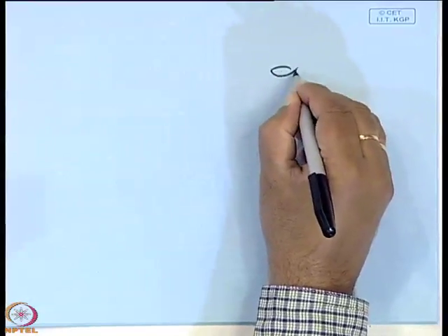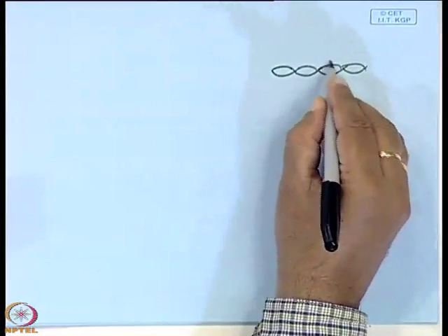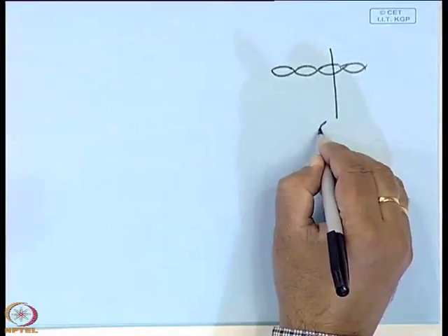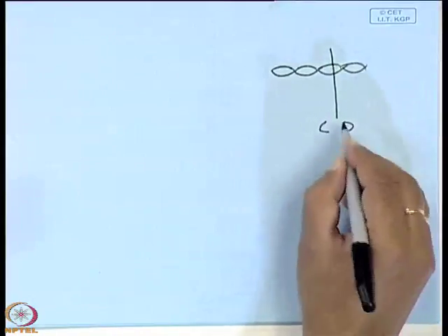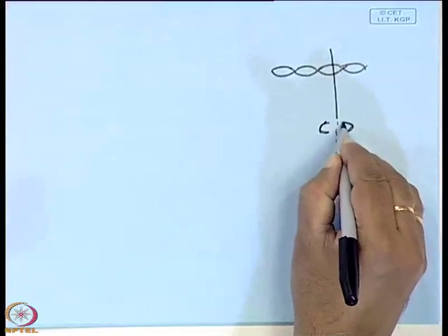Because when we talk about a wafer or a substrate, basically it is a piece from the bulk crystal. So, when you cut a portion of it, that bond is terminated. Say this is a bond. So, you break here. So, it is terminated. So, it becomes like this. So, on this surface there is an unsaturated bond.